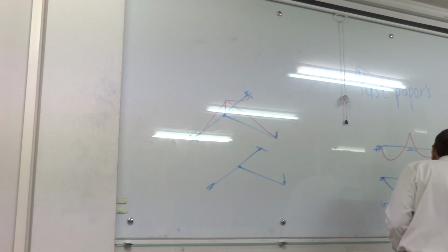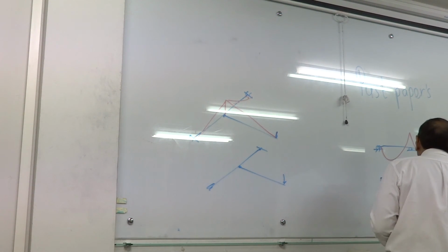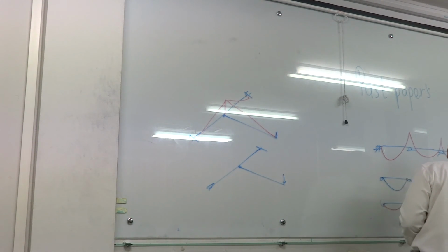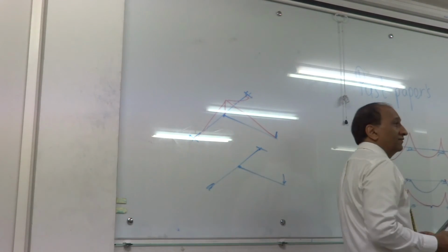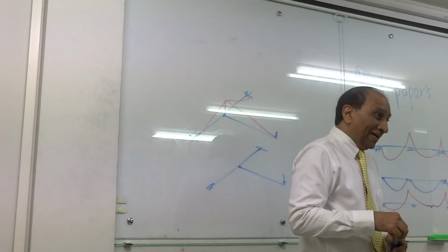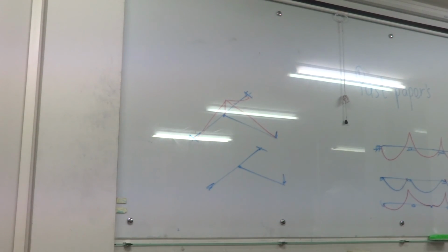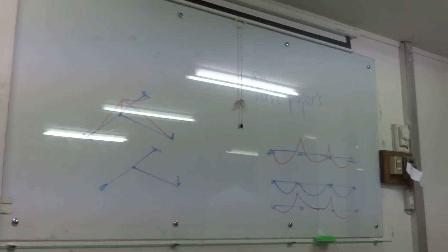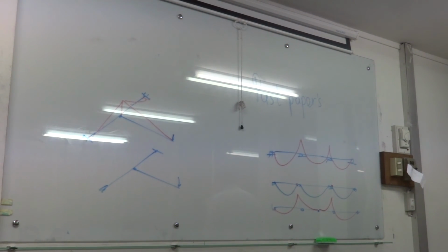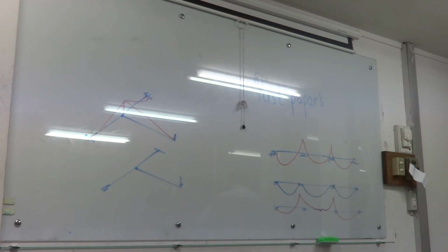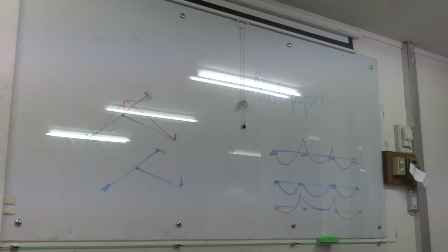Or I can say I have a hinge here. So in which case the bending moment diagram may be like this. One cantilever here, and it's still fine. Correct? So which means for an indeterminate structure, you know what an indeterminate structure is, I can choose to make it compatible, and I can choose to introduce hinges until it becomes determinate, and until that point I can play with the reinforcement and shift the moment diagrams here and there as long as it doesn't fall down. Correct? Same is the case with the compatibility torsion.